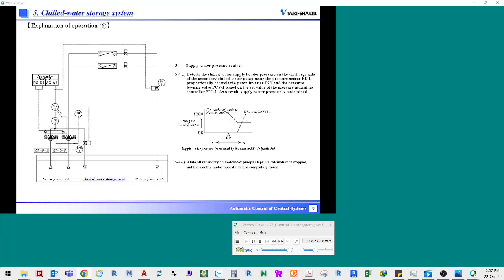The rated flow rate of the pressure control valve used under inverter control is often selected based on 30 to 40% of the rated capacity per pump. If you select the rated flow rate based on the rated capacity per pump, the pressure is controlled by the pressure bypass valve, and if you cancel some inverters, you may reduce the initial cost.